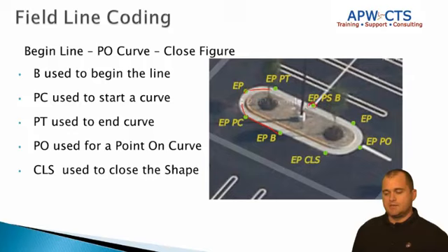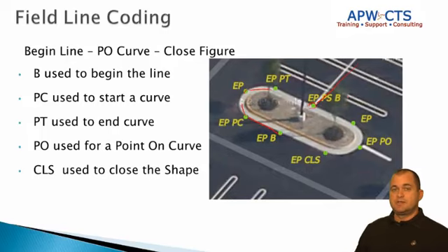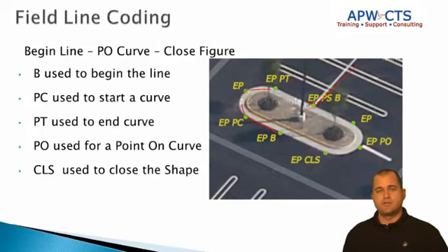And then over here what I'm doing is I'm putting an EP, but also notice that I'm double coding this. I'm putting a PSB. I'm telling it that I also want to begin that pavement stripe as it goes down and shoots off. Now we're going to come back and talk about multi-codes here in a minute, but I just wanted to show you that at this same point I can have one shot, take EP space PS for parking stripe and then B to begin that line. And then I can continue down shooting the rest of the edge of pavement.